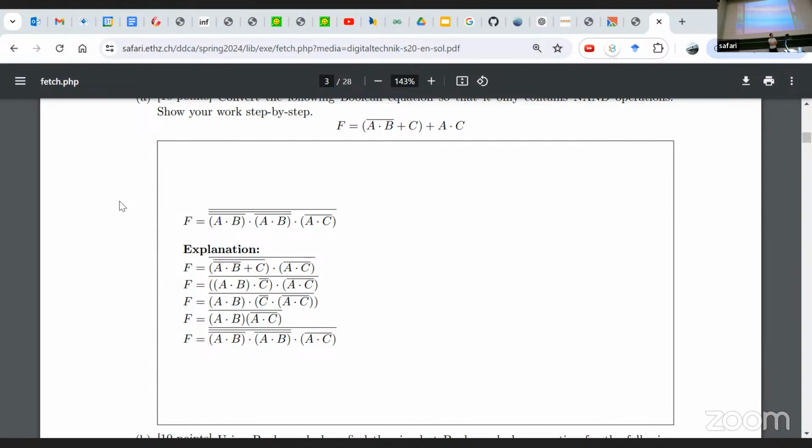Let the previous instruction go further in the pipeline so that it can write the result that the trailing instruction can use. So either you stop advancing it and artificially stop things, or you just insert something in between to artificially make a gap between them. And that, at some point, is also a hardware implementation question.